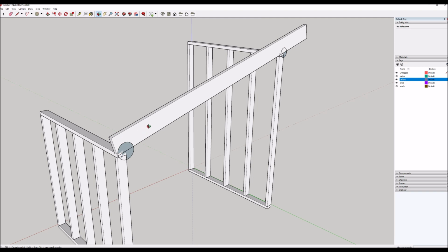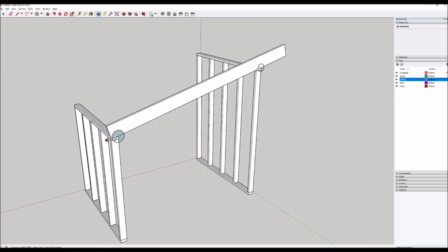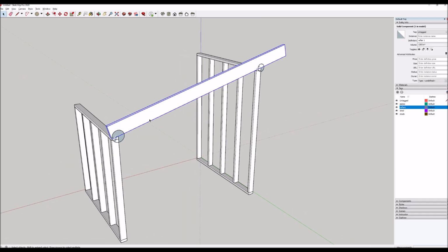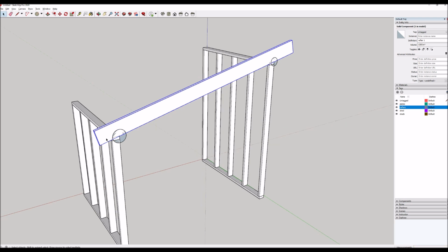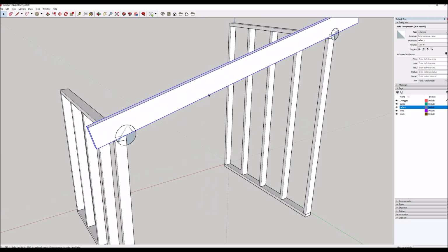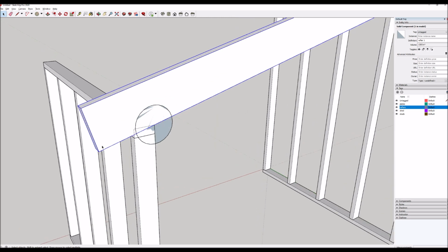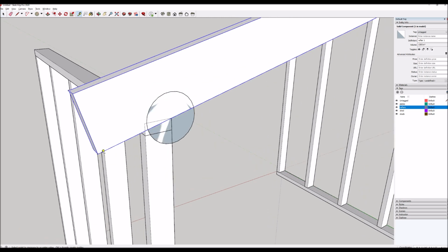I'm going to move this rafter now, and I'm going to pull the rafter off in one 6-inch overhang down at the low wall. So I'm going to take this rafter and I'm just going to click M for move, click on it at one of the edges, carefully holding the mouse over the edge, parallel to the edge, and then type 6, enter. And that moved it 6 inches along that length of the rafter. So if I were to actually measure the distance from the bottom tip to the stud, that's a little less than 6 inches because it measured the 6 inches on the angle of the rafter itself.